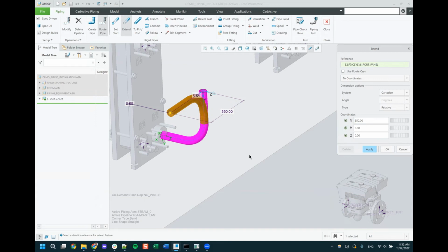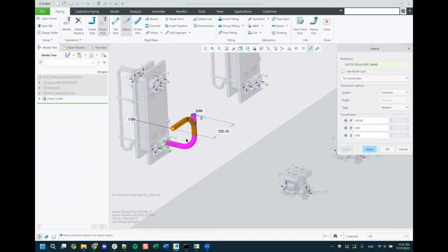Every single 90 degree will be populated with a 90 degree elbow. If it's a 45 degree, you can choose to have that filled automatically with a 45 degree elbow as well. That's something a lot of people will do if they're not going to be bending their pipes. They'll route the whole pipe using just the center lines, and then once they're done with the design, choose to, in one fell swoop, replace all of those corners with elbow fittings all at once.